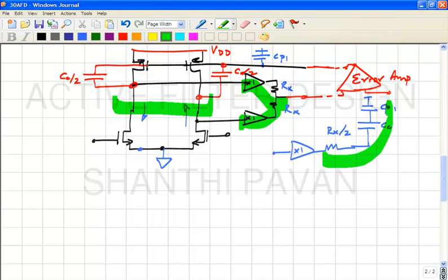The only reason we are interested in doing that is we know that this is going to form one part of the gyrator where there is inherent positive feedback for common mode signals, correct? And the one way of avoiding common mode oscillation without ambiguity is to make sure that the loop gain of that positive feedback loop is much smaller than 1, right?